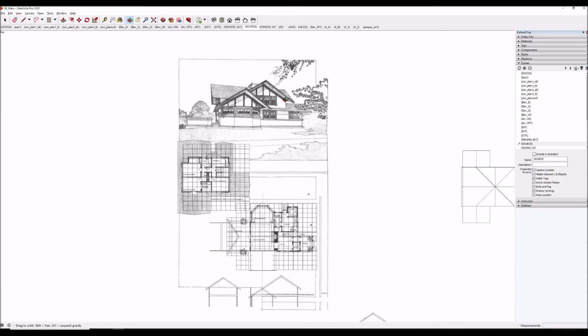And a few inches this way or that, I wasn't worried about at this point. But I needed to establish that roof line. We have a gable facing towards us, and then we have gables on either end. So what I did was I blocked out the upper floor.